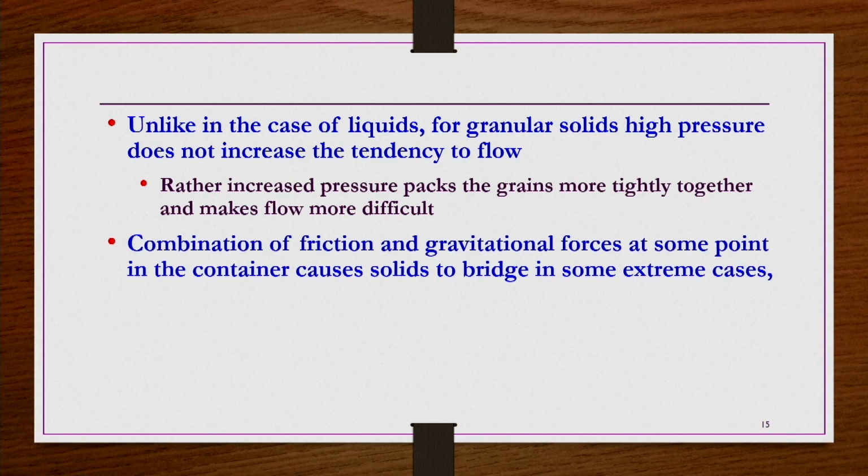So finally, the combination of friction and gravitational force at some point in the container causes solids to bridge. In some extreme cases, bridging of the material takes place, something like this, bridge-like structures. These things we are going to see in the flowability of materials. What happens when containers form such a bridge is that when you take material out from the bottom, whatever material is there is taken out,